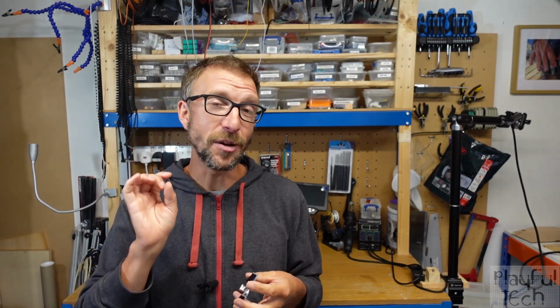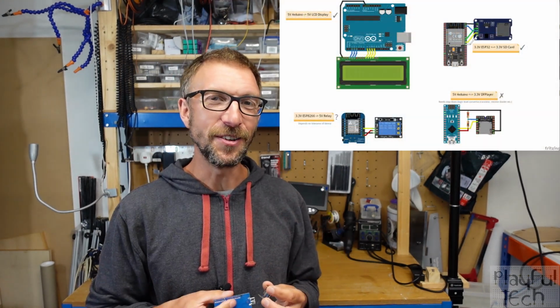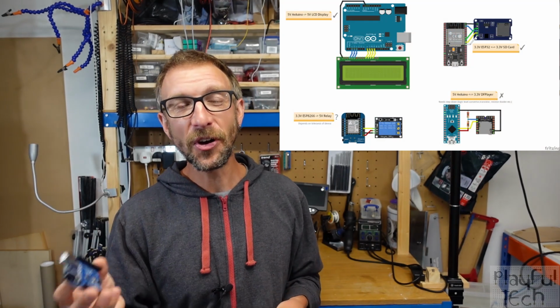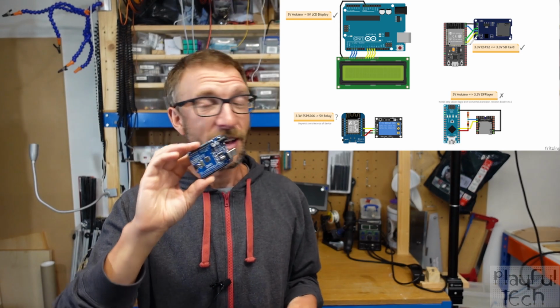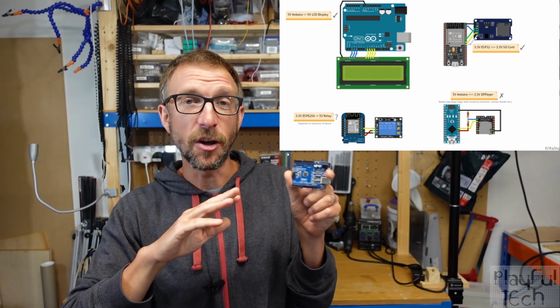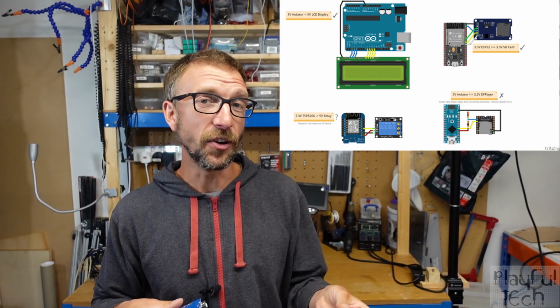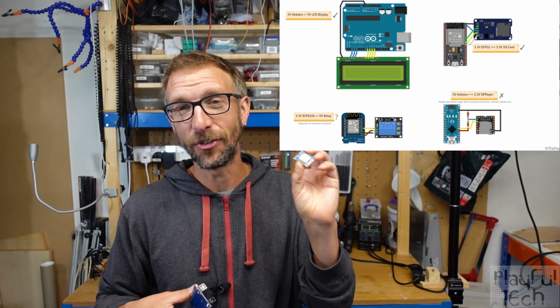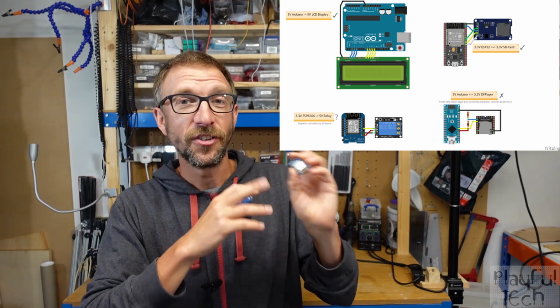Whereas GPS modules, OLED displays, SD card readers normally operate at 3.3 volts. So that gives us 4 possible scenarios. You might be controlling a 5 volt device from a 5 volt logic level controller. And this is easy. You can then wire the device directly to the appropriate GPIO pins. Or you might be controlling a 3.3 volt device from a 3.3 volt logic level controller. And that too is very easy. You can wire them directly.